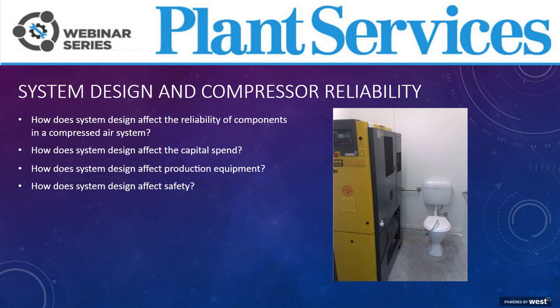I would like to say that this is not the first time I've seen a compressor installed in a restroom, but it's the first time I've seen the condensate drain plumbed into the toilet lid. That is a safety issue because the condensate comes out at 100 psi, and if the lid is up, it's going to shoot straight out.